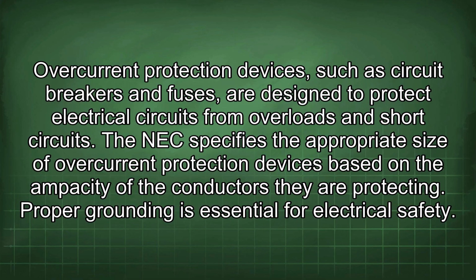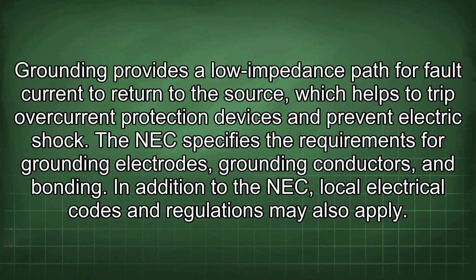Proper grounding is essential for electrical safety. Grounding provides a low impedance path for fault current to return to the source, which helps to trip overcurrent protection devices and prevent electric shock. The NEC specifies the requirements for grounding electrodes, grounding conductors, and bonding.